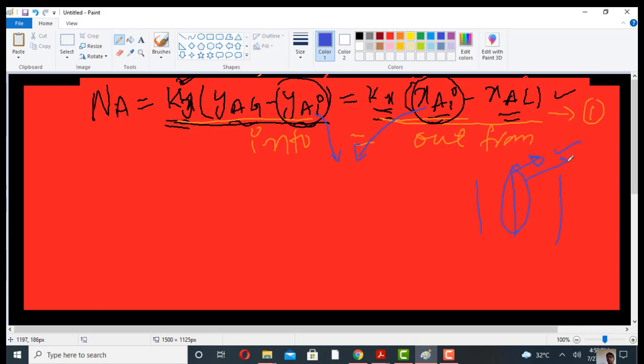We cannot take a sample from the interface and measure it with a concentration measuring instrument, but we can measure the bulk concentrations here and here. We cannot sample the interface because, first of all, it is a very thin region, second, it is an imaginary surface, and third, it would disturb the composition of the other places. So we cannot measure the interfacial concentration.